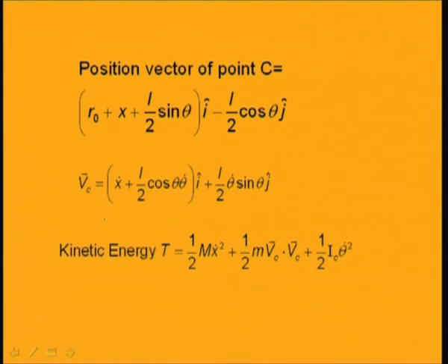Now you can find the velocity of this. You just differentiate this expression and you find the velocity as x dot plus L by 2 cos theta.